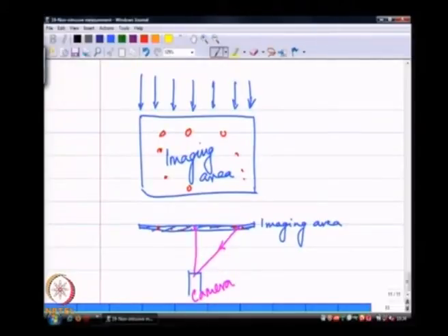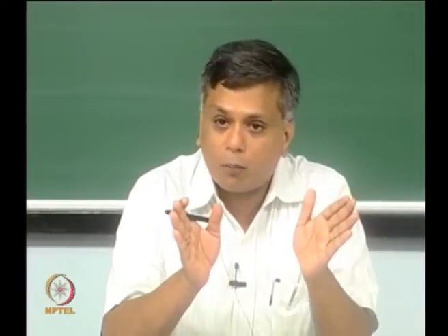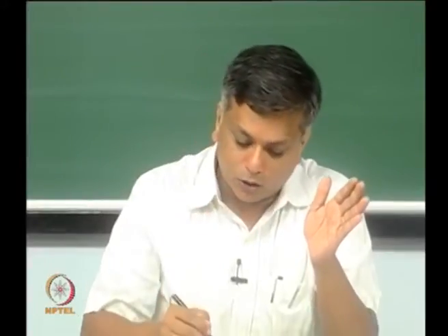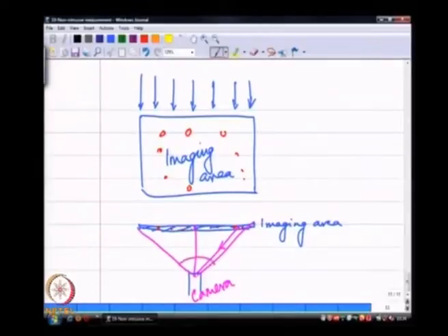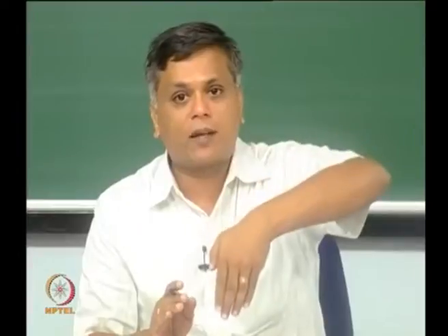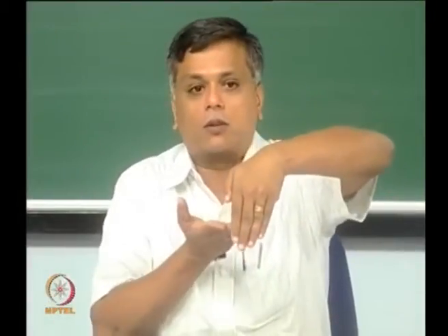Okay, so, if my field of view is much larger than the camera aperture, which is always the case, it is very rare that you are imaging at 1:1 or less than 1:1 magnification in a typical PIV application. So, you are really looking at a fairly broad region in the spray, and so this typical angle may not be as large as this schematic indicates, but it is surely not small, it is surely not 0 degrees. If the angle is nearly 0 degrees, which is the case like in a microscope, you are essentially looking at the scatter from all the drops being very close to that 90 degrees. So, light coming in from the top and scattering light towards the observer.